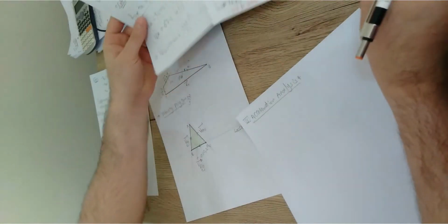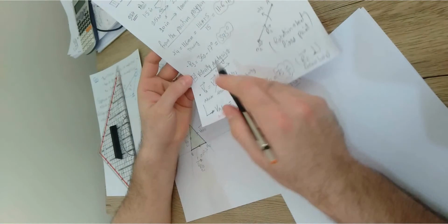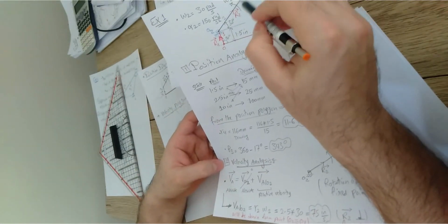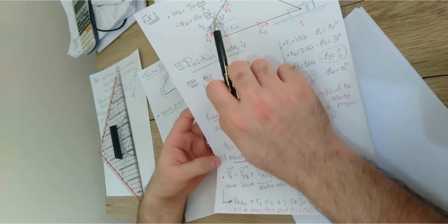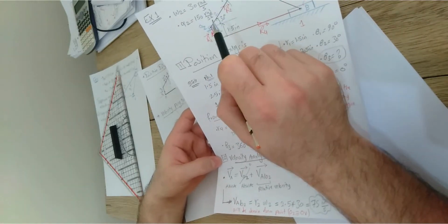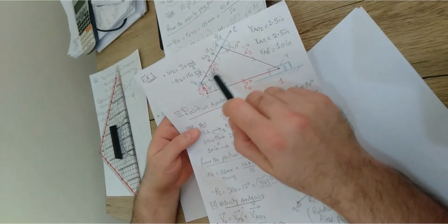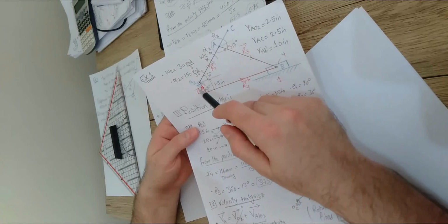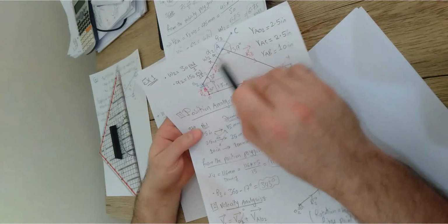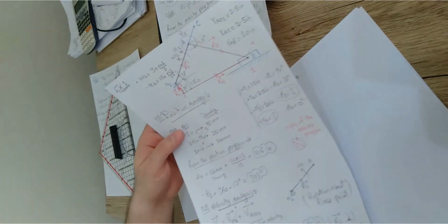So we're going to repeat the things that we did here for the velocity. We started from the link with the angular velocity that was already given. The angular acceleration here, alpha 2, is already given as 150 radian per second squared. And this angular acceleration was given for link 2, so I'm going to start with link 2. Again, link 2 has 2 points, point O2 and A. It means that you have to set up the acceleration equation that defines the relative acceleration between these 2 points, point A and O2.